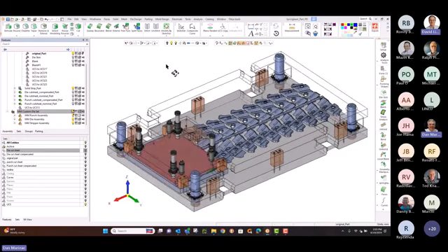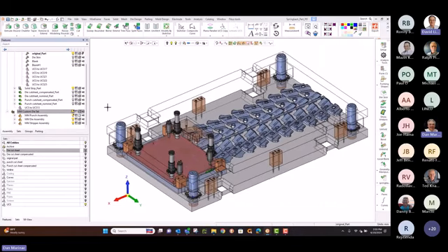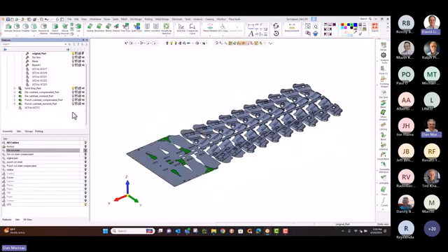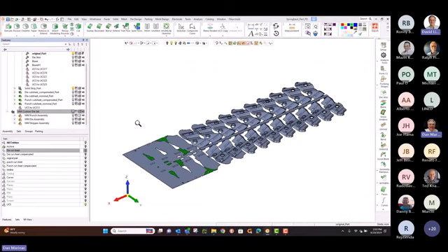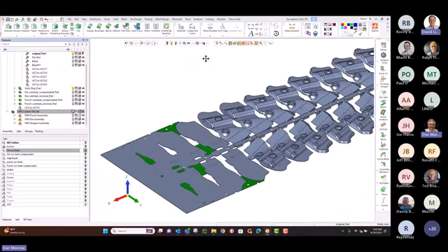So we're going to move along to the tool. Of course, we talked about using this in the quote process to understand what we're doing with the material. But here we're in process. We've got a die set laid out, and we've got our strip already laid out. So we're going to move up on the strip, and this is going to help me see where I want to address the springback issue.